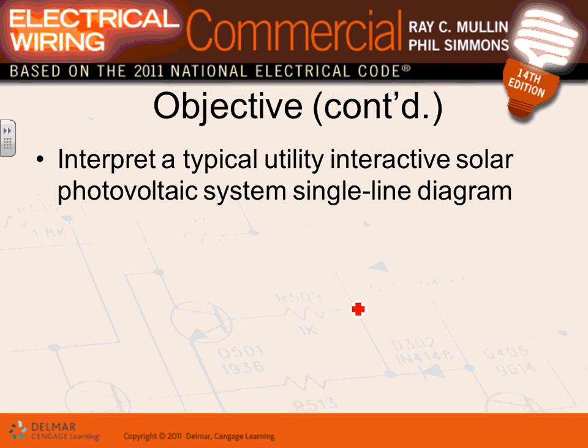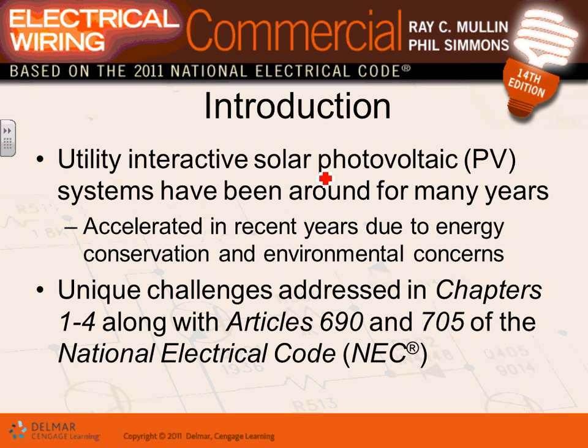You guys are designers, so you're familiar with a single line diagram or one line diagram, that's what you did yesterday with me, guys. A solar photovoltaic system has a single line diagram, which shows all the panels tied together to the combiner. You'll see what a combiner is. From the combiner you go into the inverter, and from the inverter into your power system, which is typically the grid. In between there's a bunch of conduits, disconnects and labels. That's what the riser will show.